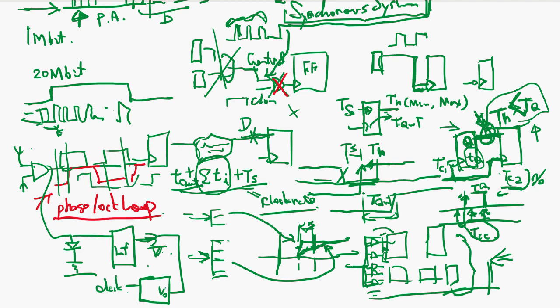The nominal is agreed 1 megahertz, but even the same 1 megahertz, it could be 1.01 megahertz. The incoming could be 0.99 megahertz. So it's not synchronizing. In order to synchronize this completely, you have a voltage controlled oscillator, and that's the clock you use for your chip.